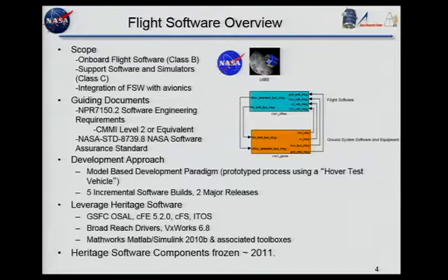This was a model-based development effort where we used Simulink as the modeling environment, auto-coded out the flight software, auto-coded out a simulation of the spacecraft separately, and developed the flight software using 5 incremental builds. And of those 5 incremental builds, build 4 and the build 5.x's were released to the spacecraft. Build 4 was an INT release, and build 5 was for the spacecraft.